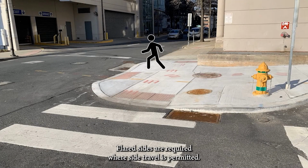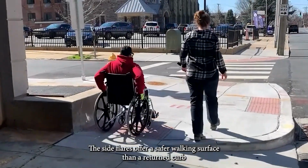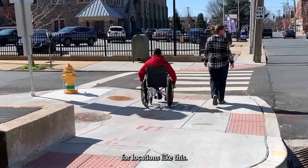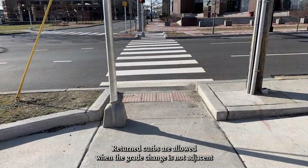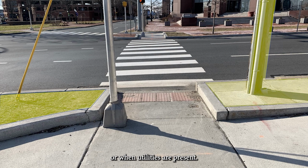Flared sides are required where side travel is permitted. The side flares offer a safer walking surface than a return curb for locations like this. Return curbs are allowed when the grade change is not adjacent to a walkable surface, such as at a buffer strip or when utilities are present.